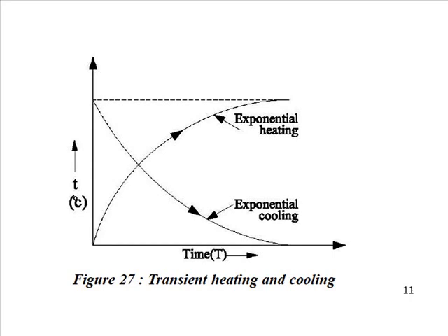The second observation is that the temperature of the body approaches the bath or surrounding air temperature Ta exponentially. The temperature of the body changes rapidly at the beginning due to the large temperature difference, but the temperature change slows down at a later stage. A large value of hA divided by rho Vc indicates that the body will approach the ambient temperature in a very small time duration.